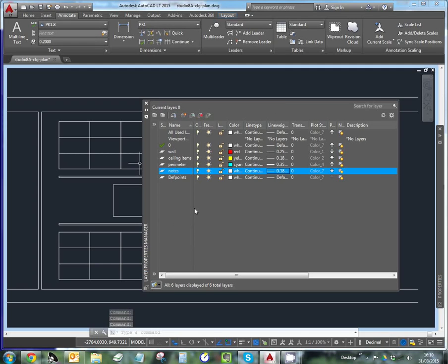We can see whether we've got these right when we do a trial print, and we'll show that later on in the tutorial. Finally, a layer for dimensions, and it repeats the layer that we last did: we're happy with those properties. Pen of 0.18 and coloured white. So let's set up our layers.